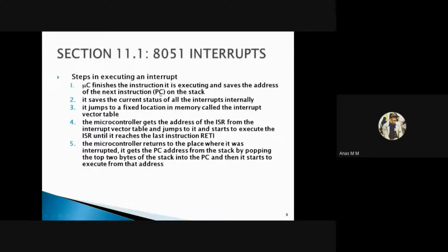Then the program counter is actually pointing to the next location where the instruction for the main program is. It will fetch that main program instruction and execute it. These are the steps in an interrupt.